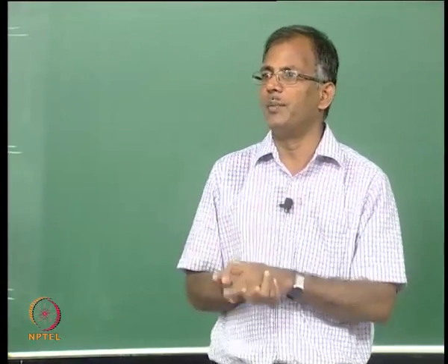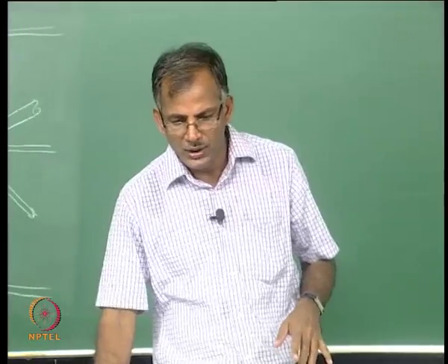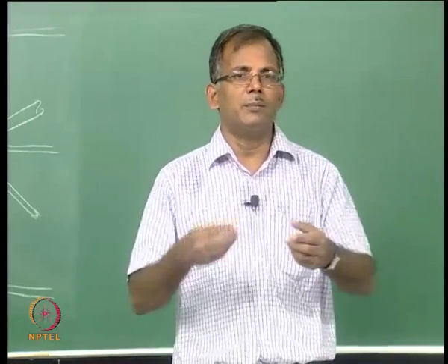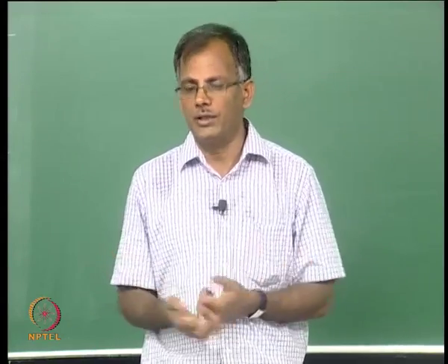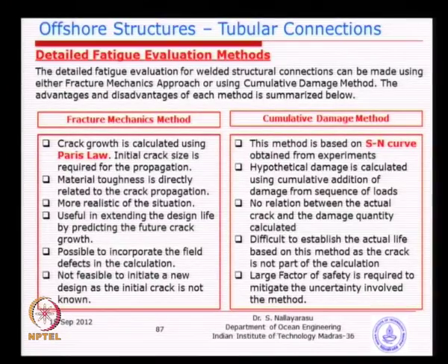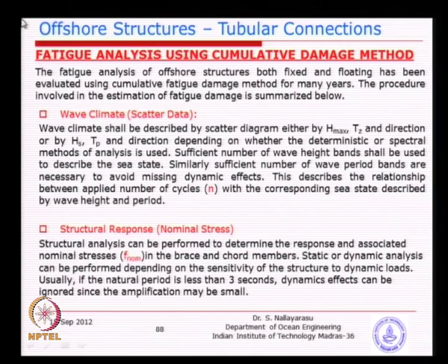The whole method is arithmetic, as long as you have the stresses calculated on the structure and simply take the number of cycles applied over allowable cycles. We will see this method in more detail. Basically, what we really require in order for this method to work is the wave climate.